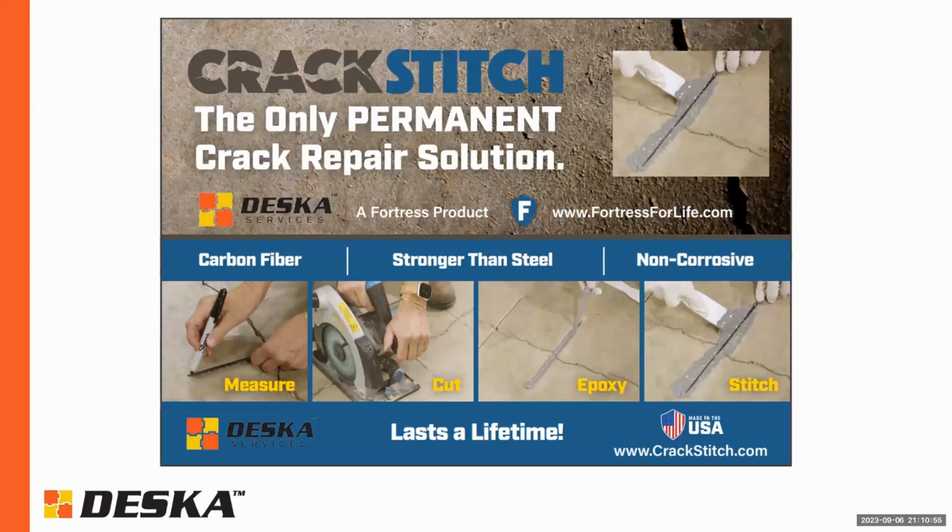In terms of cracking in concrete, a newer product that I wanted to make you guys aware of is, when you're epoxy injecting a crack in a wall or in a slab, they make these carbon fiber stitches now, and along with epoxy injecting that crack, you can actually install these stitches, and they will make that particular crack much stronger than the surrounding concrete. And so companies actually install these, and they provide lifetime warranties on the crack.